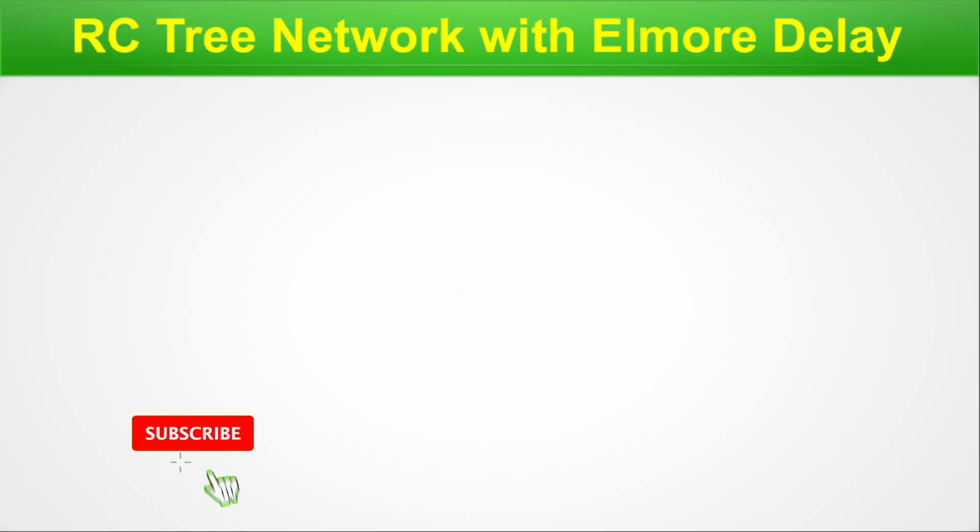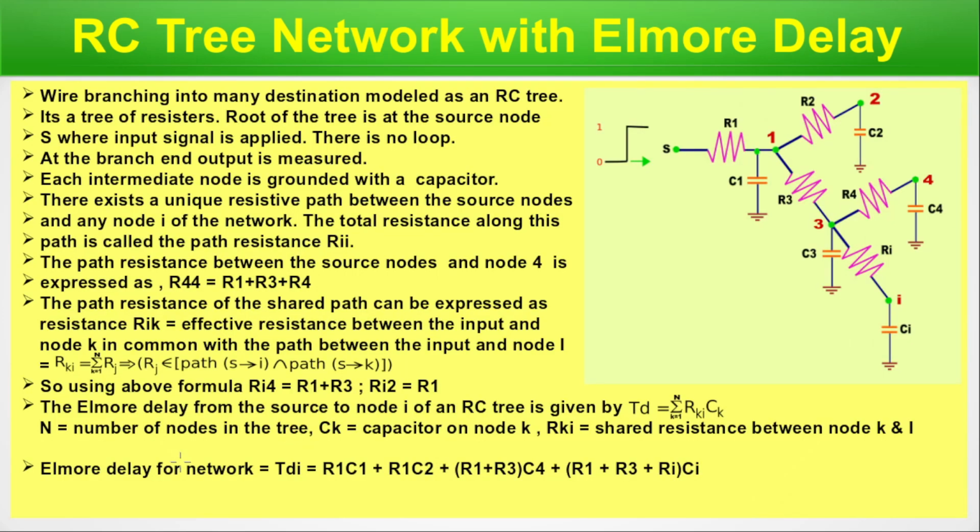So next, RC tree network with Elmore delay. Now we will apply Elmore delay on an RC tree network to get the result. A wire branching into many destinations is modeled as an RC tree. It's a tree of resistors. The root of the tree is at source node S, where the input signal is applied. There is no loop. At the branch ends, output is measured. Each intermediate node is grounded with a capacitor.